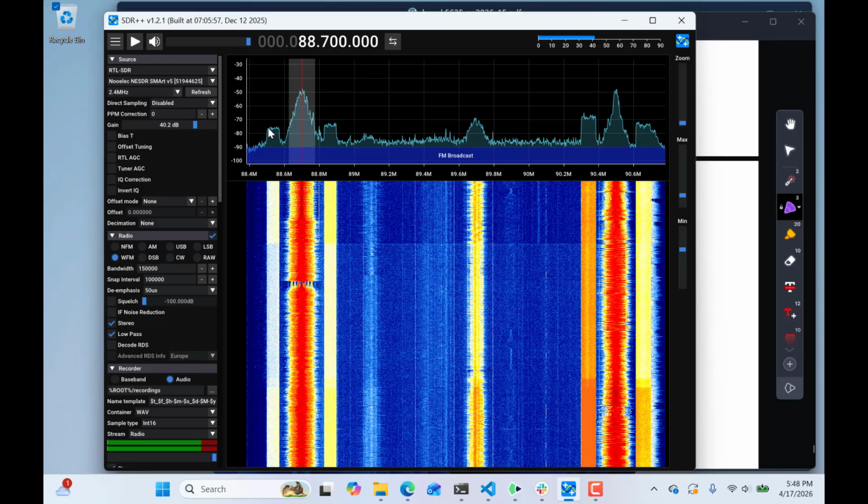But what do we see on here? We see these rectangles over here. This is HD radio for FM broadcasting. So those are signals that are being carried along with the 88.7 megahertz carrier. They're a form of frequency division multiplexing also, and those sidebands are sitting above and below the centralized carrier. So unless you have an HD receiver, you can't do anything with them, and to support legacy, they're not interfering with the primary FM broadcast. There could also be other subcarrier signals because the FCC allows that in FM broadcasting.